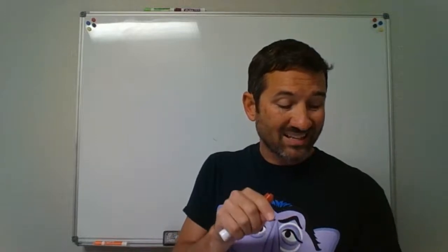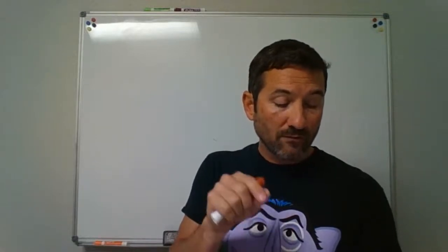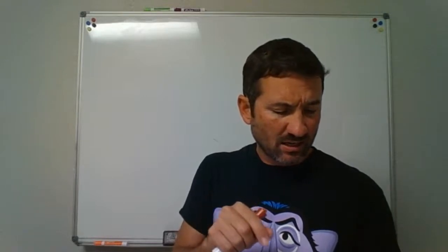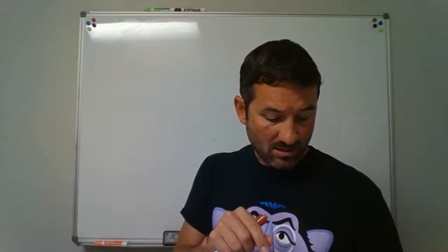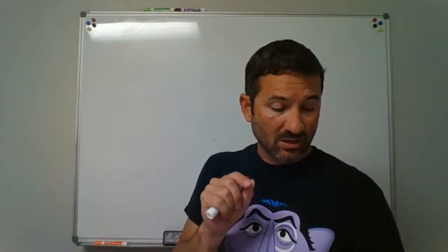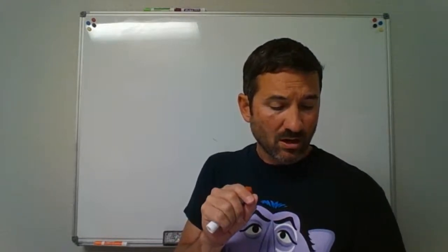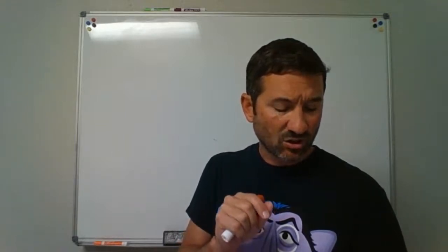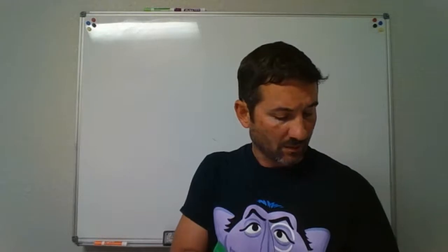Also, when you get down to 906.2, vents other than the stack vents or vent stacks are going to be half the diameter of the drain served, but no less than 1.25 inches. Right on that one.